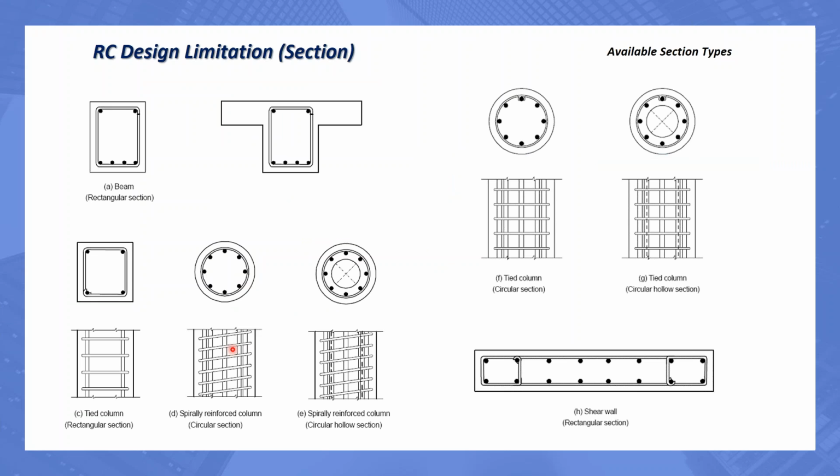So for RC design, we have these available sections. For beams, rectangle and T-shape are available. For columns, solid box, solid round or hollow circular sections are available. In the case of walls, we can design straight walls only for now. If you need to consider, for example, a combined wall or core wall that doesn't have a straight shape, we can use the Design+ option for this. Later I will show you the design procedure for combined walls using Design and Design+.